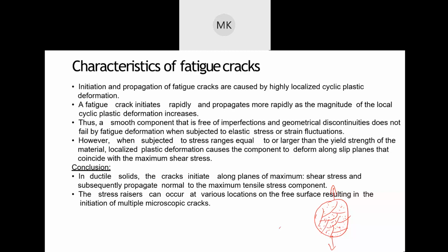So all these mini cracks are not going to do much to the failure of the material until a surface crack starts, which is going to be the major crack which forms, because all fatigue cracks start from the surface. So once a fatigue crack starts from the surface, this crack is going to grow in the direction of shear plane or in the direction of dislocation, which is basically going to be the 45-degree angle.